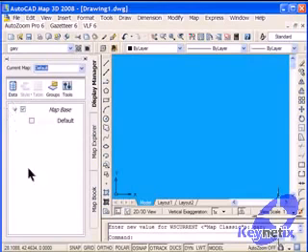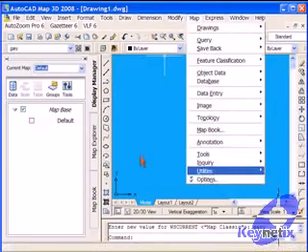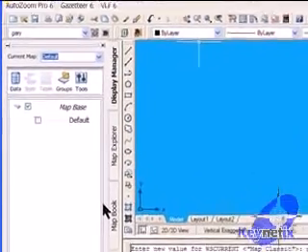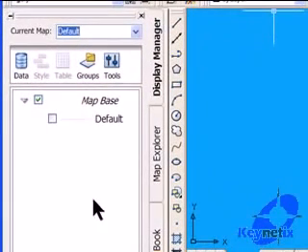Now we can get to this area on the left hand side. This is known as the task pane, and if the commands are not available in the map pull down, they'll be available in the task pane. The task pane itself is divided into 3 separate areas. The display manager, which is how data appears, what colour lines it is, the order in which it appears on the screen, how it's hatched, does it use transparency.